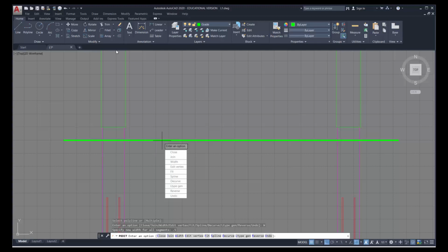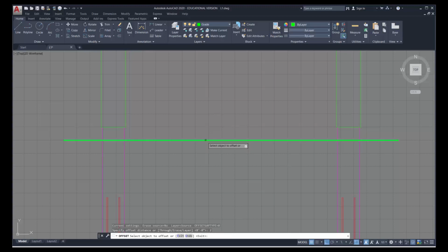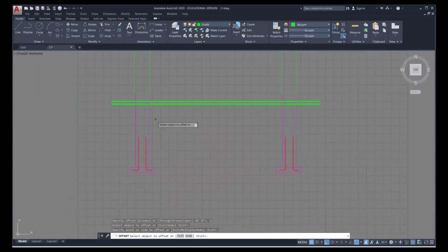And with grade, the way we represent it is with two lines. Now I'm finished with this command, so I'm going to press Escape. I'm going to click on the offset command, type in 2 and enter, select the polyline, and then move below. When we measure things, we always measure to the top line of the grade, not to the second one. The second one is basically symbolic to identify that it is in fact a grade line. Now everything below here has a certain property to it. It's hidden. Now we haven't talked about line types before, but we're going to right now.